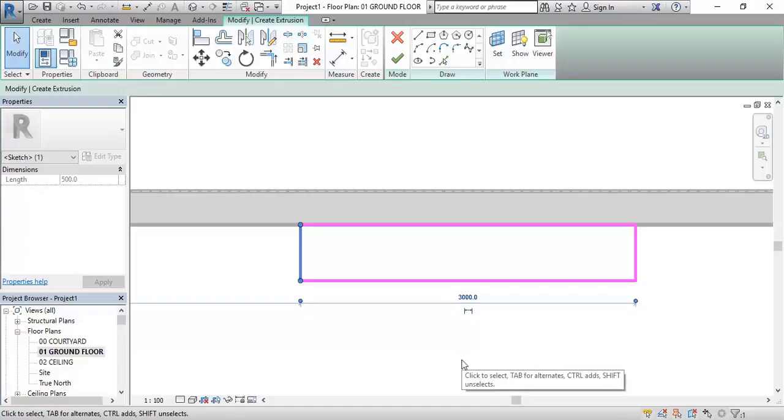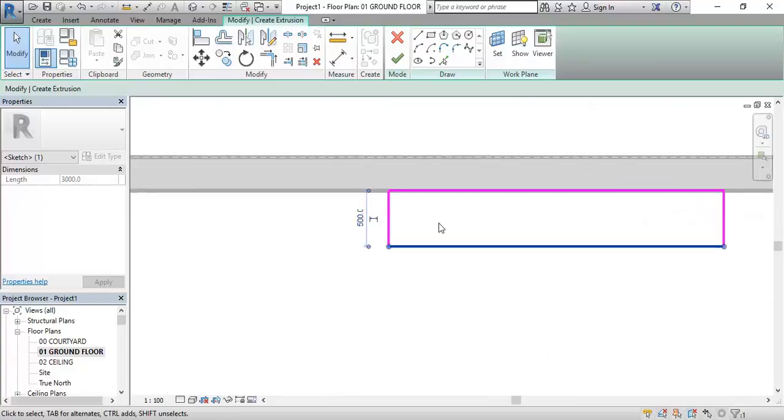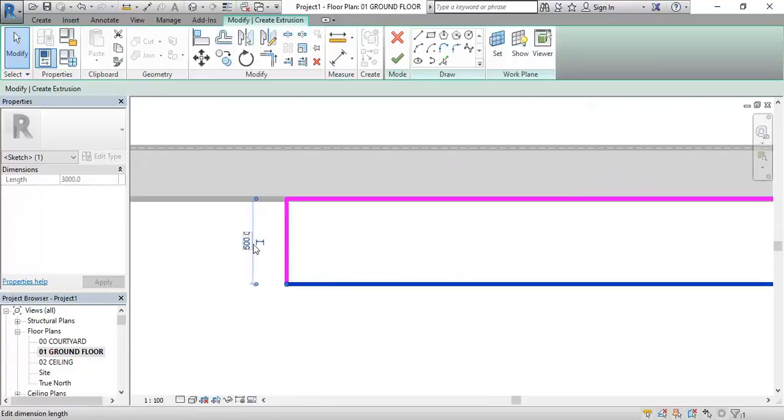Yeah, just go back to the architecture tab, and then click on the arrow on the component, and then model in place again. I'm just going to make it a random length, but the width, or the depth, sorry, should be a particular size. So I'm going to make it 600 all up. That means if I make this 550, so I want to do it flush, so I have my detail, and I've just put it away.